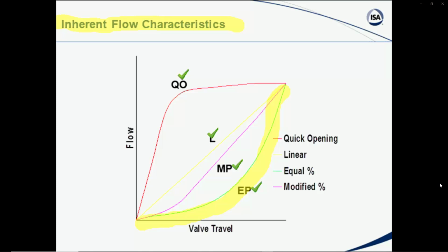And so it depends on what type. As I said, equal percentage is probably 80% of the applications, linear maybe 10, and the quick opening maybe another 10. But notice on the quick opening, you have to be very, very careful in using that, because in the very first early part of the opening, you get a real high flow rate, and that's why that high gain, that's why it's called a quick opening, whereas the others give a little bit more of a change that's characterized as they proceed in their throttling capacity.